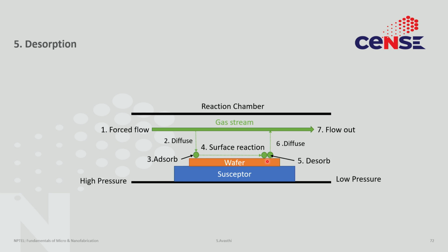So, there are some products being formed when CVD is occurring, right. There are some side products, and those side products must now desorb again through the boundary layer out into the gas stream and get pumped out, right. On top of that, often these other components, for example hydrogen, might do their own side reaction onto the surface, and those side reactions might cause some products that must desorb, etc. So, let us talk a little bit about this desorption process.